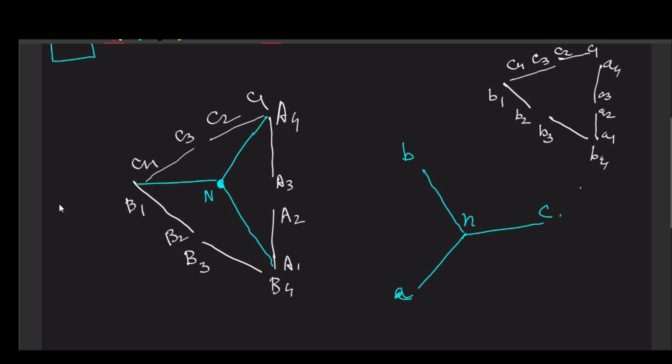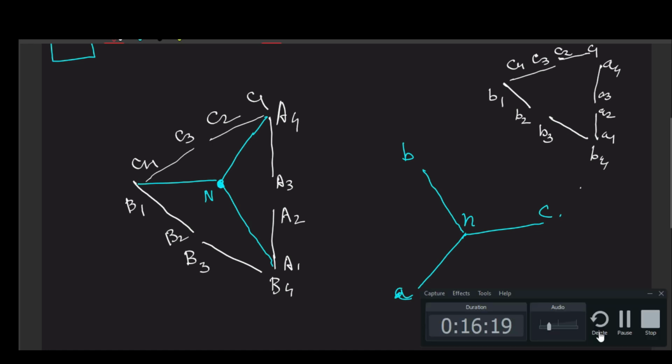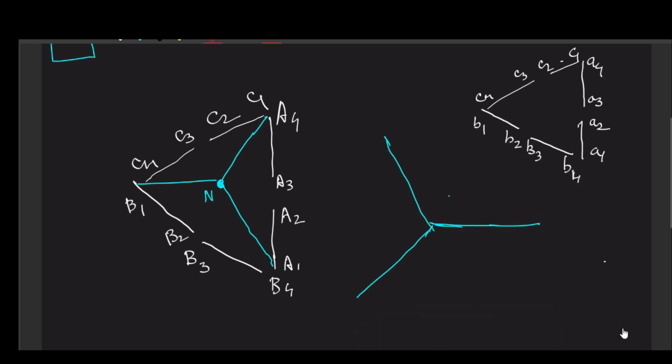So now how should we place them? The big question is how should we place them? Now I was just drawing this figure correctly so that we can utilize it without any further issue. See, here A4 is connected with the voltage source. So definitely if you want a 180-degree phase shift, you have to connect your terminal with A1.